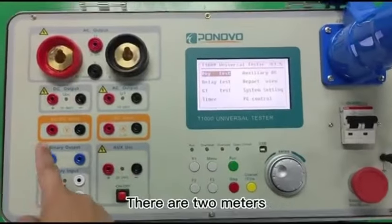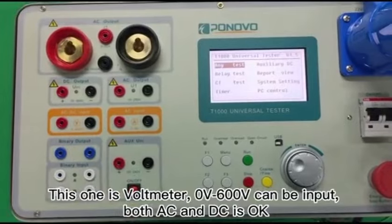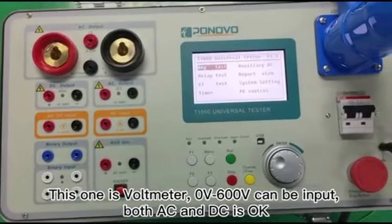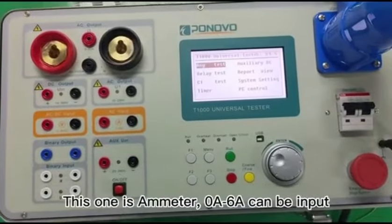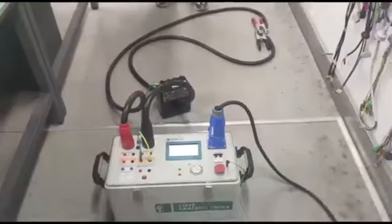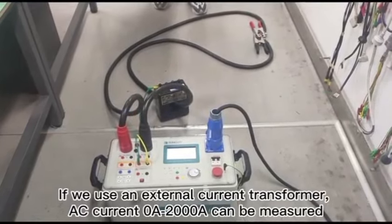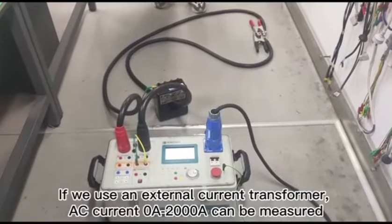There are two meters. This one is voltmeter. From 0 volt to 600 volts can be input. Both AC and DC is okay. This one is ammeter. From 0 ampere to 6 amperes can be input. If we use an external current transformer, AC current from 0 ampere to 2000 amperes can be measured.